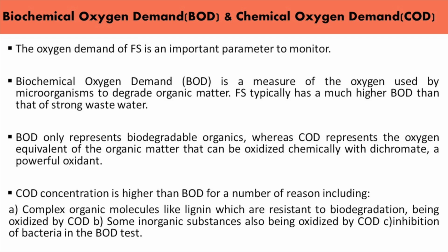BOD only represents biodegradable organics, whereas COD represents the oxygen equivalent of organic matter that can be oxidized chemically with dichromate, a powerful chemical oxidant. COD concentration will always be higher than BOD for a number of reasons, including complex organic molecules like lignin are resistant to biodegradation but are oxidized by COD.